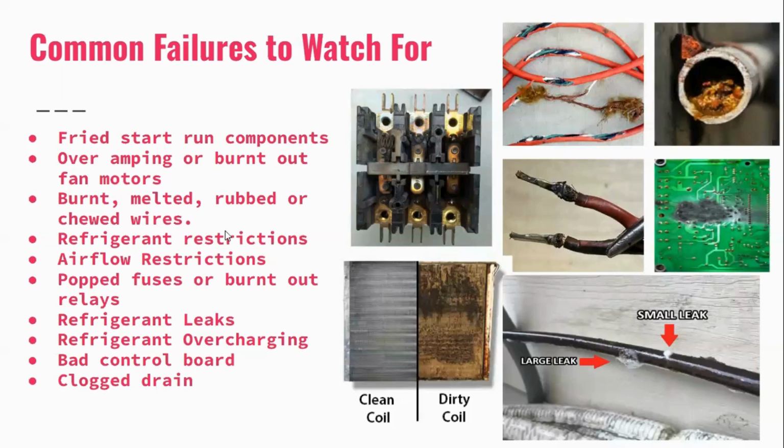That happens a lot. Also, mice love to live in outdoor units. Indoor units too, but I see them far more often in outdoor units. I actually just had one where I didn't even have enough length of wire. I had to splice. I hate splicing more than anything. We did it safely, but I don't recommend it. So always check for mice. Even if you're just there for a coil cleaning, open up the electrical compartment after, because 9 times out of 10, there's either a mud wasp nest or a mouse nest in there.